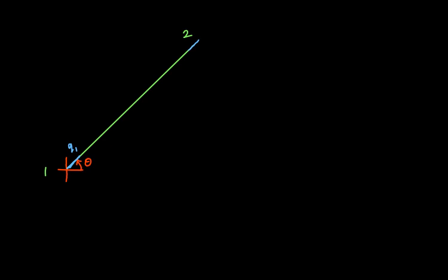So defining the stress is very easy because stress is simply Young's modulus into strain. Maybe I can start with that definition. Stress is equal to Young's modulus into strain. And what is the strain? It is change in length, which is q2 minus q1 by convention, divided by original length, which can be L. I can rewrite this expression as capital E into 1 by L